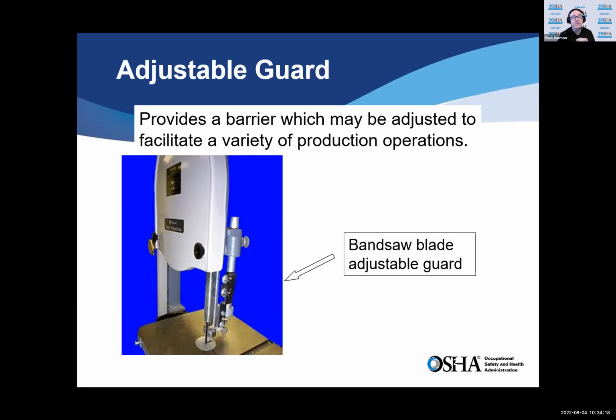And again, this is another example. I sometimes see these machines and they're new machines and they don't have that particular guard on it. And I say, hey, you need something on that. And again, can you fabricate your own guards? I don't have anything that says you cannot do that. I would say the guard should be fabricated so as to be substantial and so that it will provide the protection you want. So I guess what I'm saying is if it's made out of metal, that's good. Sometimes I've seen people make guards out of other materials.